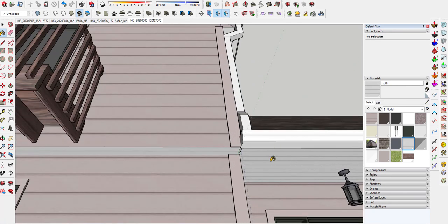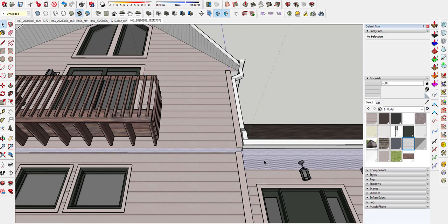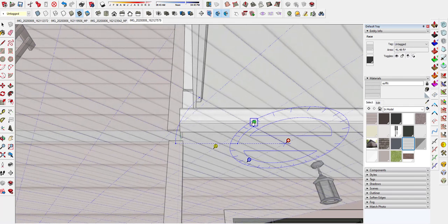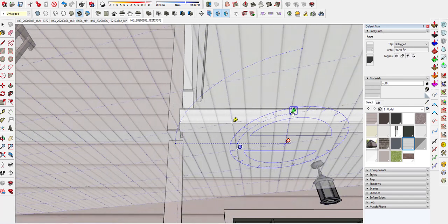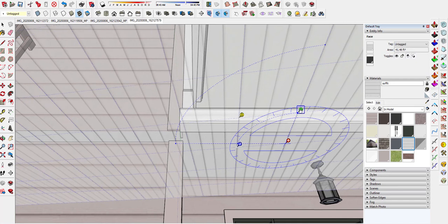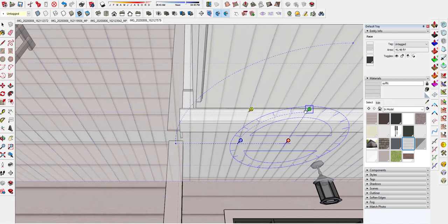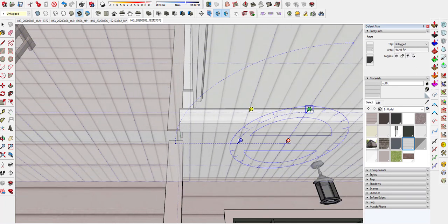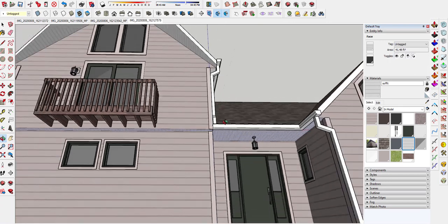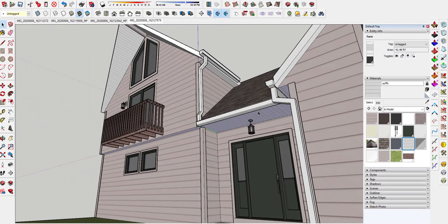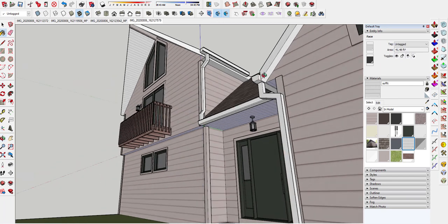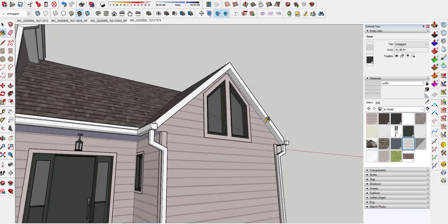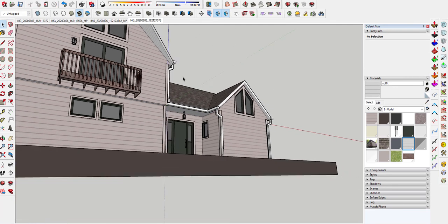Now this went the wrong way, right? It's going the other way, so select texture position, and I'm just going to go along. Now as you notice, there's these little arcs that are created. This is actually little points. You want to be on this inner arc always, and it'll snap to the red axis, but you want inner arcs always because this will be twice as big. And this will be the exact same size, just a different angle. Done. Select that surface there. Paint here the underside. Paint the other underside. And that's good.